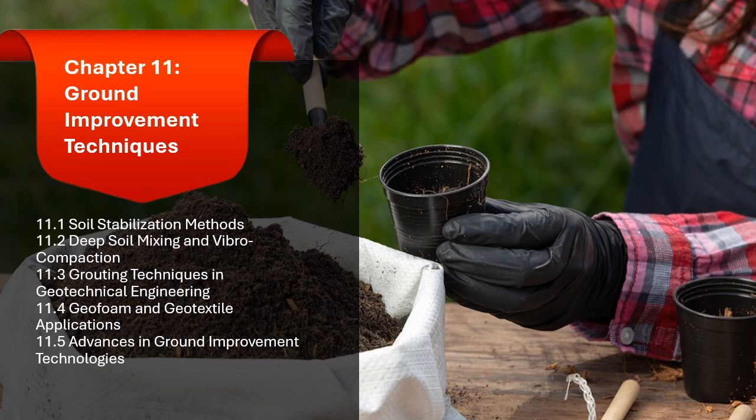1.3.1.5 Compaction grouting with superplasticizers. This type of grouting technique involves the injection of highly fluid grout mixtures, including superplasticizers, which help to enhance the grout's flowability and increase the efficiency of the compaction process. Superplasticizers allow the grout to penetrate and compact fine-grained soils, such as silts and clays.